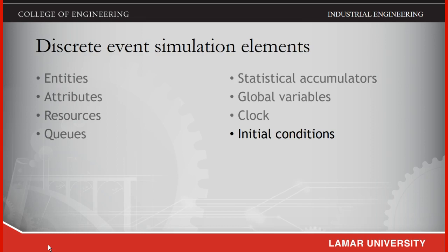So if we start a simulation and the simulation has no entities in the system, we need to allow it to run for a little while before we can actually say, okay, now the entities have been flowing in the system and the queues are typical now, and we need to cut that, what we call warm-up period in the simulation. So initial conditions may determine some of these aspects in the simulation control.